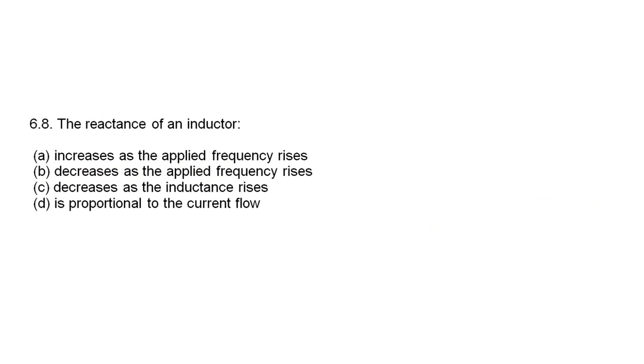Question 6.8. The reactance of an inductor, and I haven't got the formula there for you now, increases as the applied frequency rises. That's true. I don't have to read any further. I'll highlight it now, because XL equals 2 pi FL. And the reactance does increase as the applied frequency increases. In fact, it increases in direct proportion. So if the applied frequency doubles, the inductive reactance doubles.